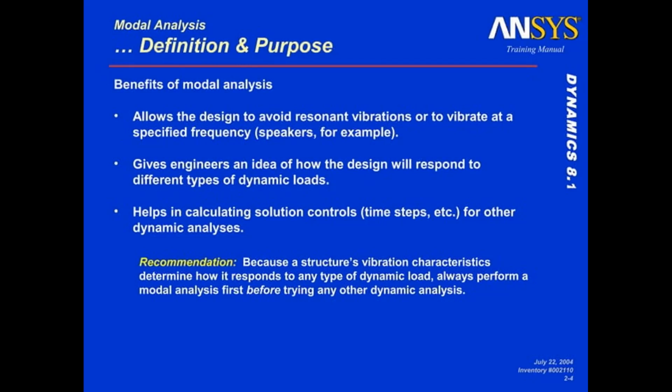Recommendation: because structural vibration characteristics determine how it responds to any type of dynamic load, always perform a modal analysis first before trying any other dynamic analysis.